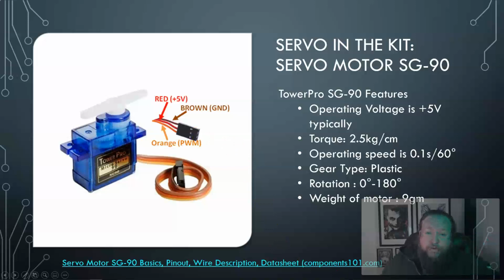They only rotate from 0 to 180 degrees, and they weigh about 9 grams, which impacts how many you have and the weight overall for your device. And the operating speed is roughly 0.1 seconds per 60 degrees.